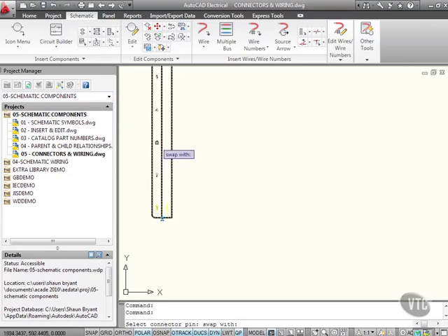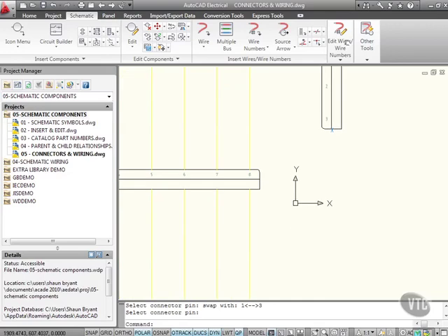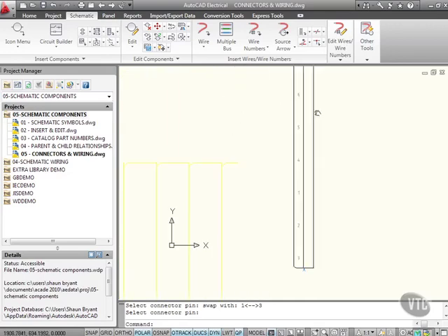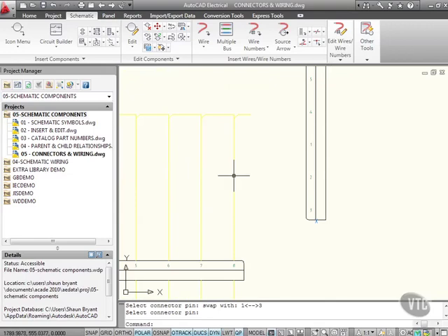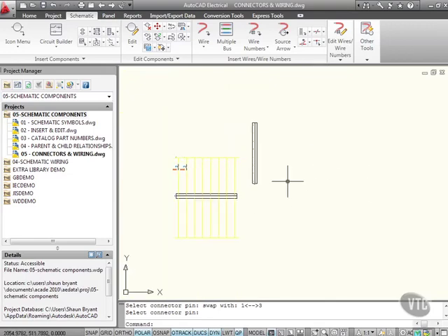with, let's say 3 there, can you see I'm swapping the numbers? So it depends on where those wires go. I'll just press enter there to finish. But your wires obviously disappeared because I've rotated that and changed the numbering. So you can see there that because that wire was in space, it was inconsequential, and when I rotated it, the wire actually disappeared. It's not there anymore.